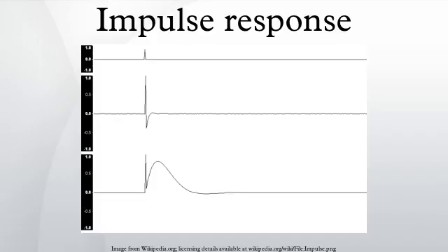Loudspeakers: an application that demonstrates this idea was the development of impulse response loudspeaker testing in the 1970s. Loudspeakers suffer from phase inaccuracy, a defect unlike other measured properties such as frequency response. Phase inaccuracy is caused by delayed frequencies or octaves that are mainly the result of passive crossovers, but are also caused by resonance, energy storage in the cone, the internal volume, or the enclosure panels vibrating.